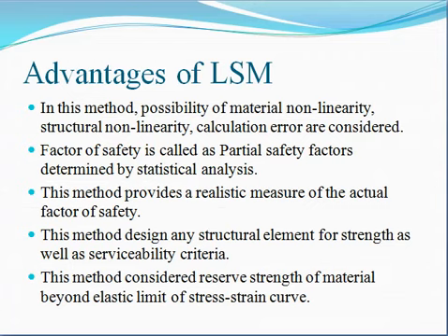Okay, and these safety factors are not fixed, unlike the working stress method and ultimate load method. In those methods the load factors and factor of safety are fixed for a particular type. But here we can adopt safety factors, called partial safety factors, for individual loads. That is, it is different for many types of load, that is dead load, live load, wind load. Again, for different types of material we have to use different values.